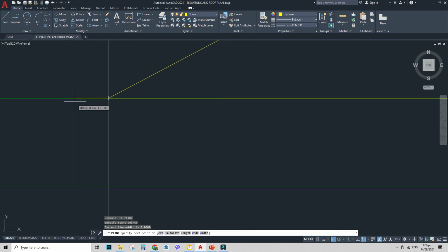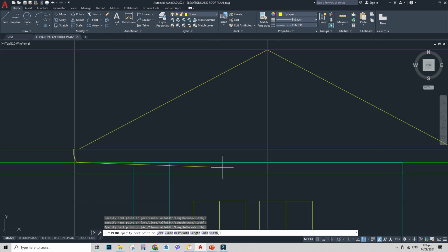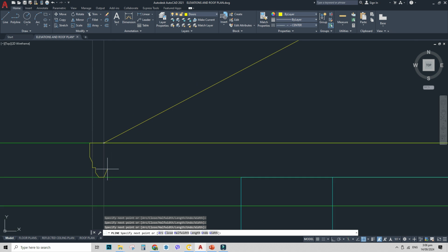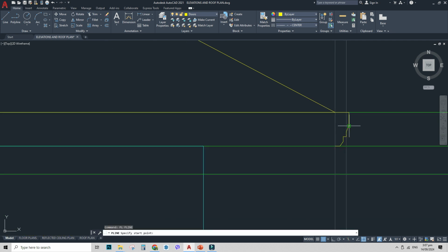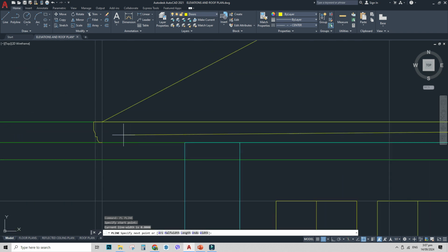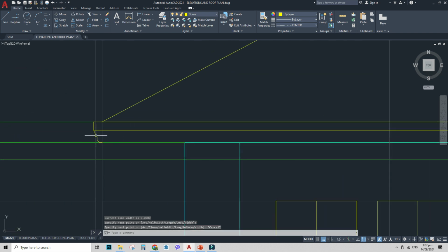PL. Just follow this specific rectangle here. And then I'll stop the ortho. That's it. You need to terminate here so that, actually, you need to do it like this and then type MI, and then click on the midpoint, and then click, no, don't forget that, type PL, and just plainly put that here.